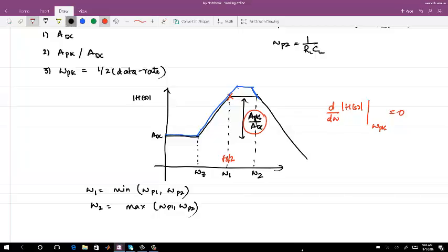And the other thing is, the way I have plotted here is as the Bode response, right? So you can say, if I do not want a higher peaking, a local maxima, I can have omega p1 and omega p2 at the same frequency. If they are at the same frequency, let's say the same as omega 1, you will have this kind of response, right? Let's assume this is minus 20 dB per decade.